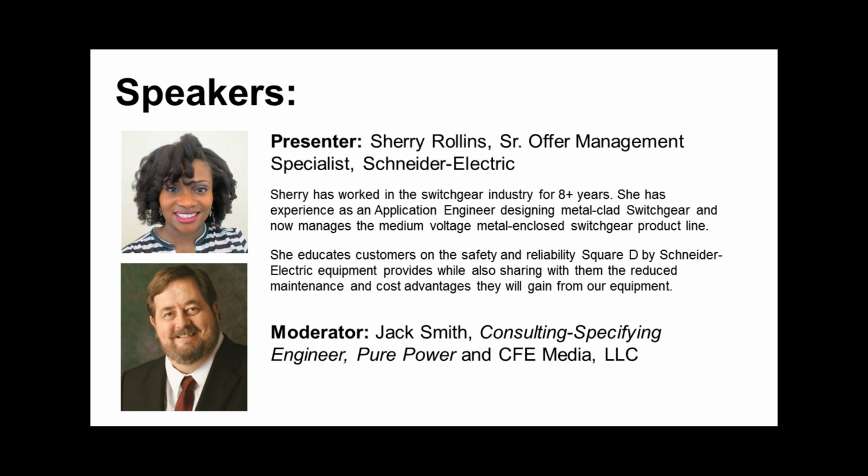I think the thing we need to convey is what you'll see in fixed-mounted switchgear, because it's smaller, you will typically have less space. Historically, air-insulated switchgear has been very large, and real estate hasn't been a premium. You've had all this space for very large protective relays and complex electromechanical devices. Well, the good news is we have migrated from electromechanical devices in most parts of the country, and these new electronic devices are so small and so capable that it shouldn't be an issue.